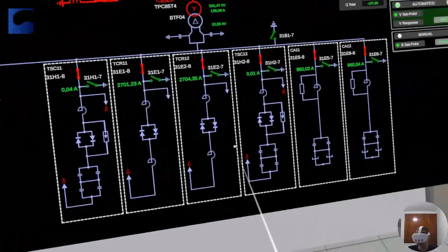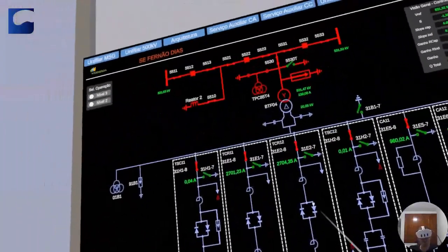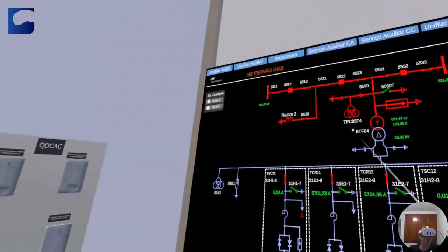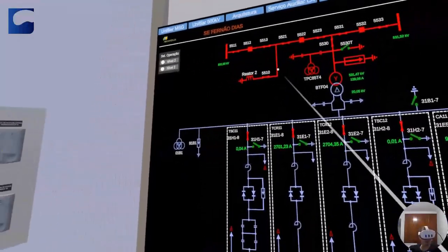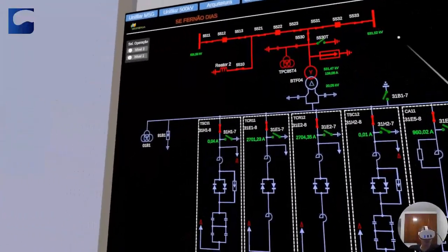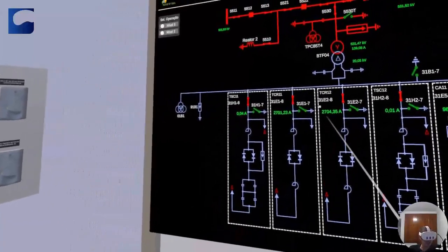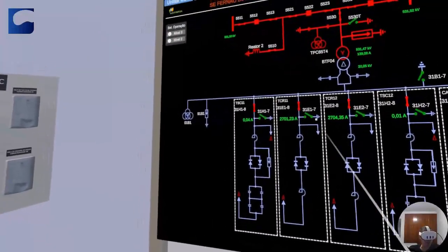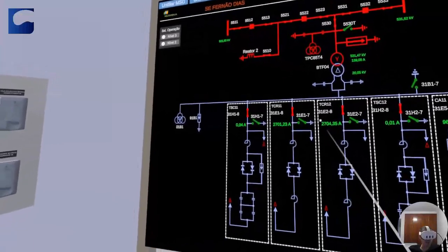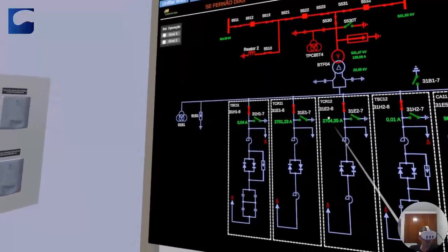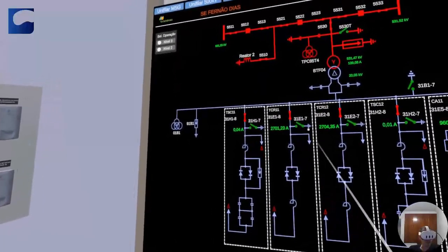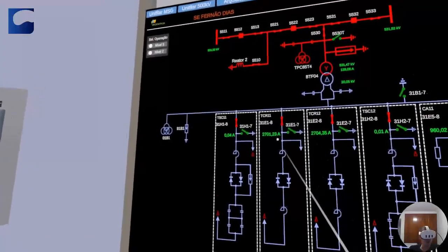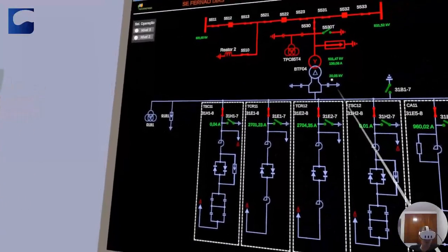And now guys, look at this. The system has a voltage that requires compensation, and at this moment, it needs to bring in reactors. So it activated both reactors with 2,700 amperes in each one. Why is the current so high? Because the voltage is lower, 20 kilovolts.